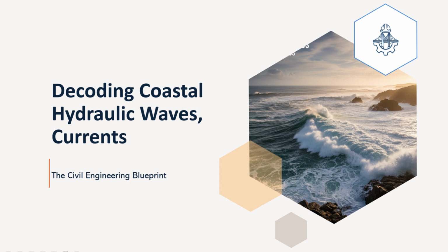The cosh k(d+z) and sinh k(d+z) terms are crucial here. They contain the vertical coordinate z and dictate how the velocity magnitudes change with depth. In deep water, for instance, these hyperbolic functions cause the particle motion to decay rapidly as you go deeper, which is why a submarine at depth barely feels surface waves. At the seabed, at z = -d, the vertical velocity correctly becomes zero, as we'd expect since there's no flow through the solid bottom. That was our boundary condition.